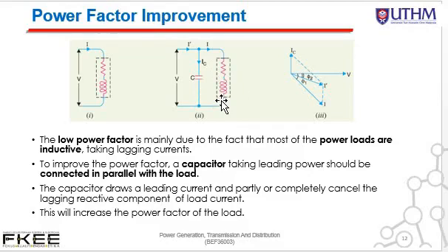This will result in a bigger power factor value but a lower power factor angle. Figure 3 depicts the angle phi 1, which is the initial power factor angle, and phi 2 as the new power factor angle after we install the capacitor in parallel with the load.